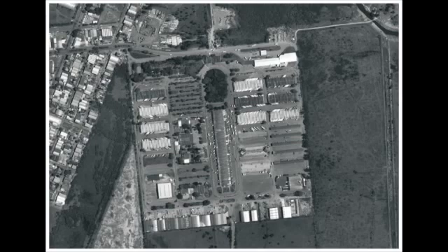The most notable building of the complex is the Growers' Pavilion, whose 77 double curvature vaults with skylights cover a width of 47 meters with a span of 30 meters and a length of 230 meters, totalizing 13,000 square meters approximately. The building was completed using only one movable formwork. Dieste also worked in the Traders' Pavilion and the vehicular entrance portico.